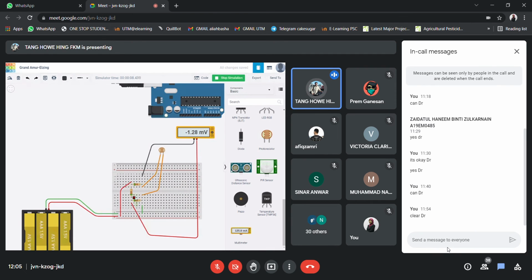And you can see that once I set this 506 ohm, the voltage further decreases and is very close to 0 already. It's 1.28 millivolt. But in real life, we can't really get such customized resistors. Standard resistors, most probably we are able to get 500 ohm.